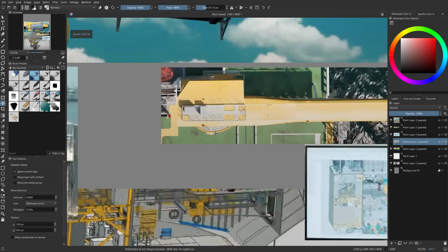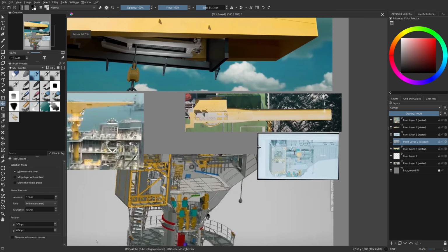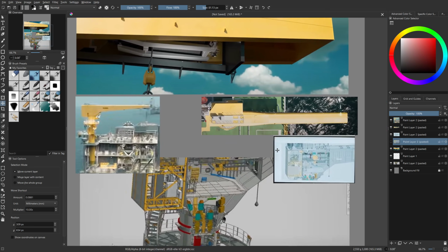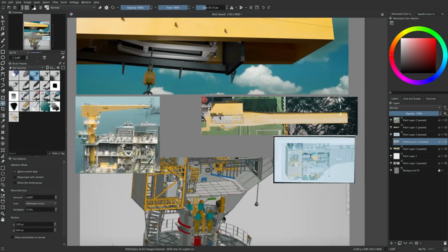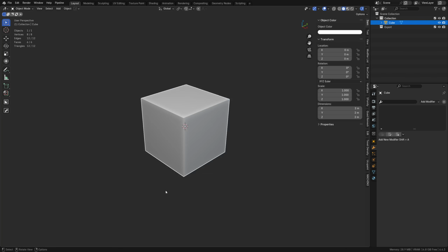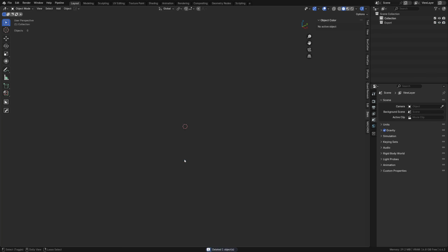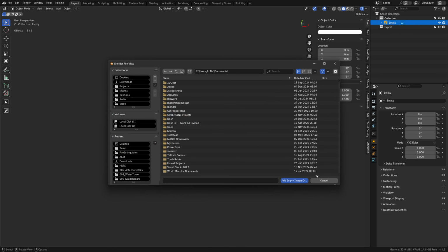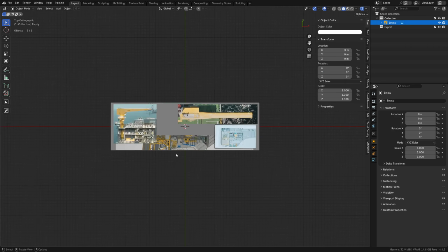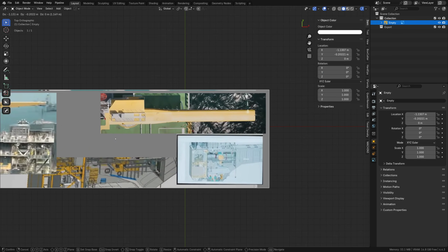There are little peculiarities when working in perspective and off images you have to pay attention to, and that's one of them. So all I'm going to do is take this into Blender real quick. I'm just copying and pasting with the paste image add-on, but basically you can just save it out and then Shift A, create image reference, and load it up. It'll come in something like this, right? Now, we know we have the top here.